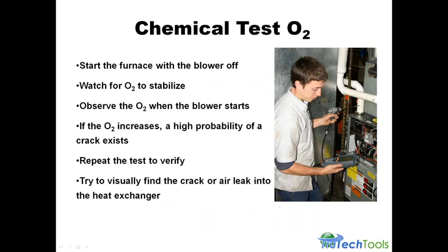When the main furnace blower, not the induced draft motor, but the furnace blower, turns on, it's going to start to pressurize the ductwork, right? That pressure is pretty high in that duct system, and it's going to force air through that crack into the heat exchanger. If our O2 starts to increase, there's a high probability that you got a crack in that heat exchanger, and you can repeat this test to verify.